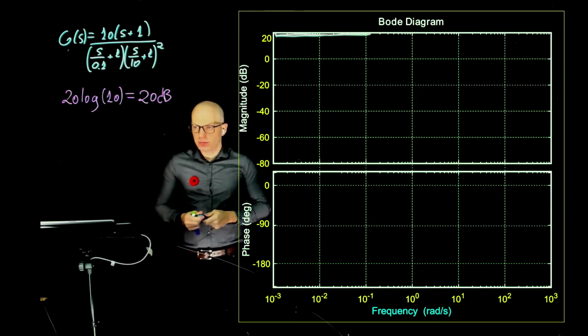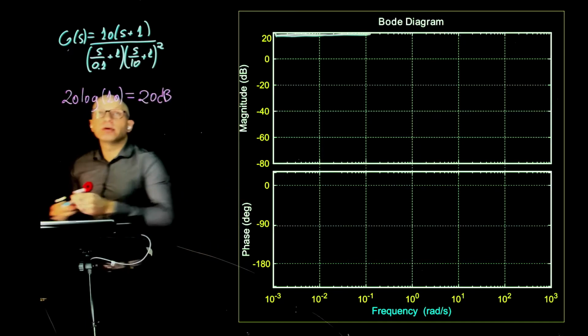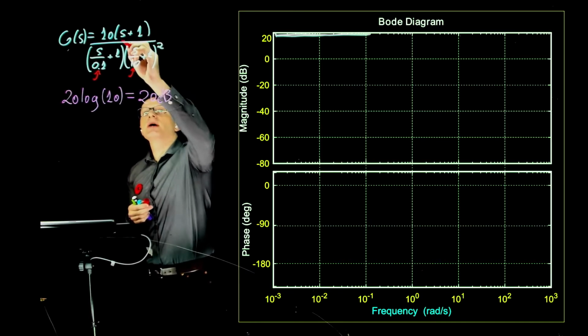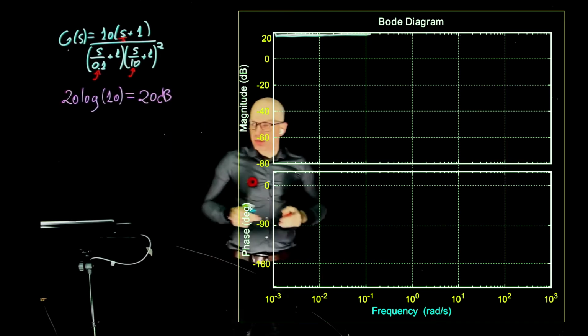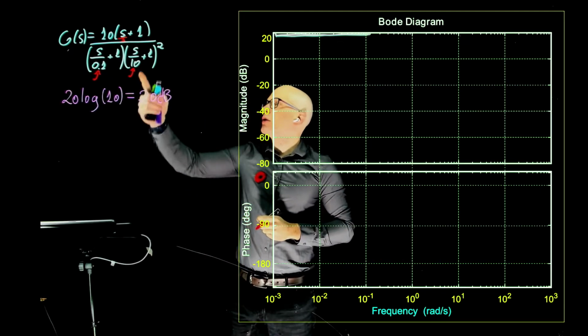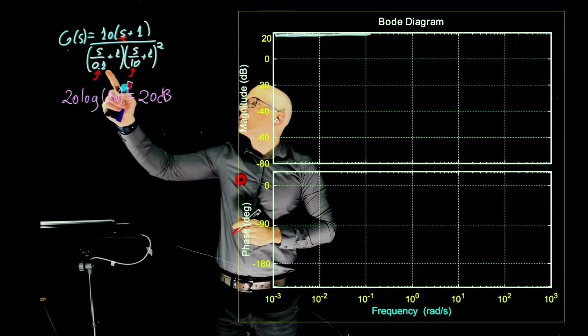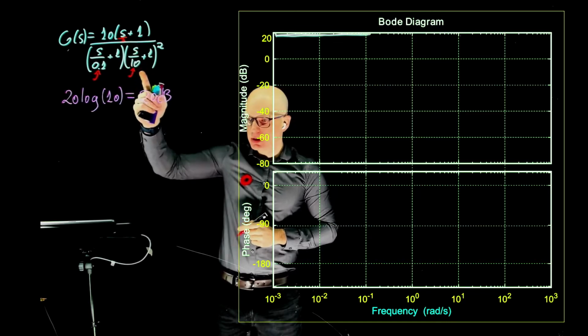From the pole, how do you decide it's 10 to the -1 rads per second? Yeah, so for the pole, we can see the cutoff frequency is right there. This is one cutoff frequency, this is another cutoff frequency, and s divided by 1 here is another cutoff frequency. All right, so these are all the cutoff frequencies, whatever divides s plus 1. Okay. Nice. So this is the first one, then you go to 1, that's a zero, and then you have a pole at 10.